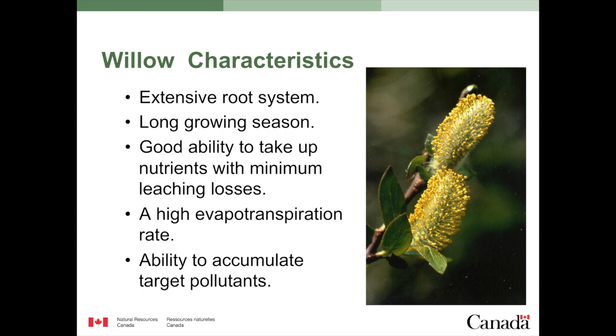Ability to take up nutrients, we talked about that. High evapotranspiration rate, great if you're trying to process a lot of water. If you're water limited, it might make it a little bit more challenging to grow it out of its optimum range, where you need precipitation to meet your water requirement. And ability to accumulate target pollutants. So you have contaminants, some heavy metals, cadmium, nickel, and zinc are preferentially picked up by willows. You can use the willows to pull those things off your site.